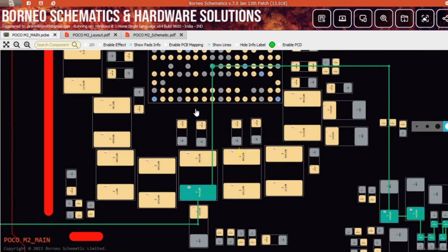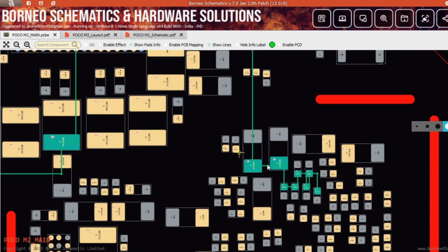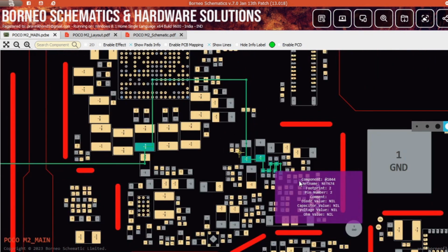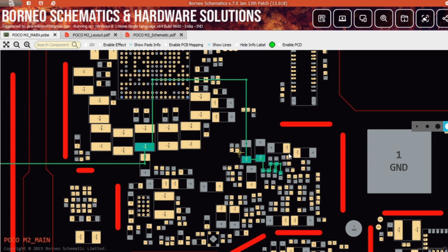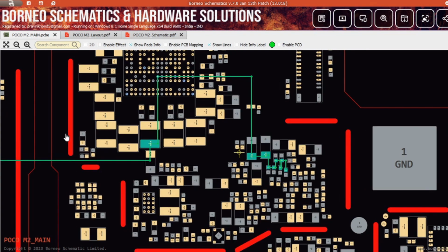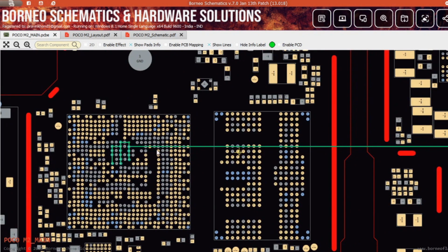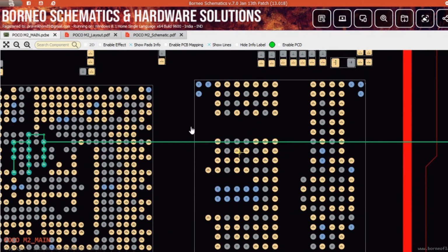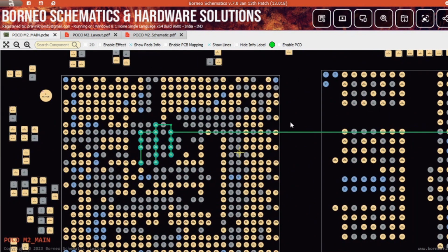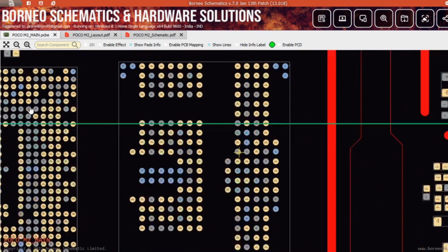Right? Now this line is also connected to some capacitors nearby. These capacitors are directly connected between a power IC and the CPU. This line also has a V processor voltage. Multiple balls are connected, and the same rules apply here. If any one ball does not connect to the CPU for any reason, your phone or your CPU does not boot, right? Your phone does not work.